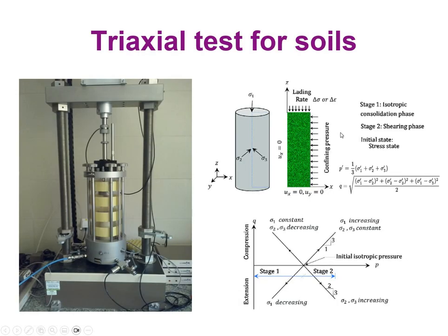Finally, I wanted to mention that when we are dealing with geotechnical engineering, we usually need to run more complex tests than tensile tests, because we don't test soils for tensile stresses unless we are doing some sort of research specifically for that matter. So in the case of soils, we produce a sample that is tested in something called a triaxial test, where we can apply forces in the horizontal and vertical direction, and we can apply pressure because this is a chamber that is filled up with water, for example.